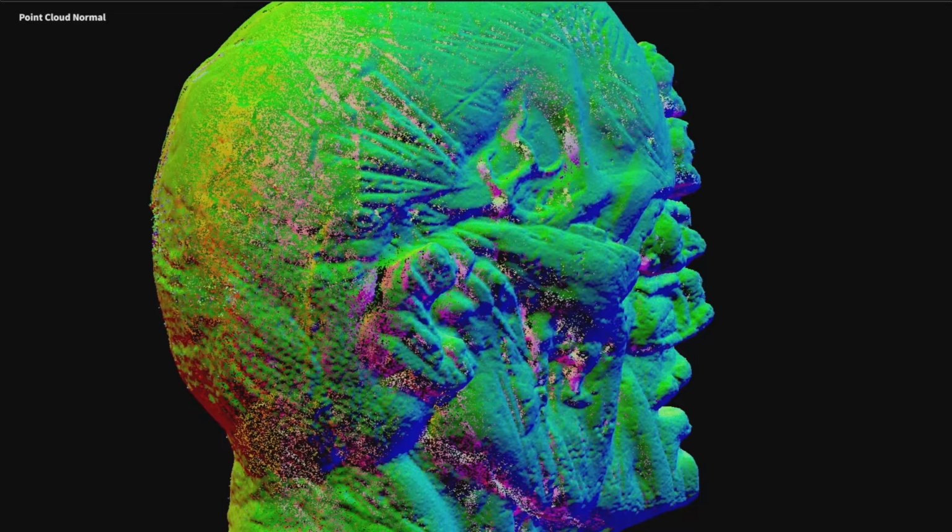If you set the hint for the observer's position to the location where the scanner was, you should have perfect normals. The other mode, called local propagation, will try to make the normals of neighboring points consistent with each other. This often works, but it may require you to pre-process the input, and you may need to fidget with other parameters because it needs a smooth, dense cloud of points to work well.